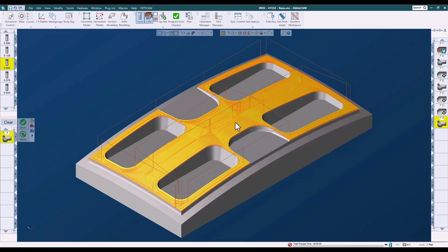And this is going to be similar to what we talked about on the constant step over cut. The way that the borders of this shape are being offset, you will end up, especially with a shape like this, with areas where the toolpath gets isolated, and so it has to retract to reposition to a new area.